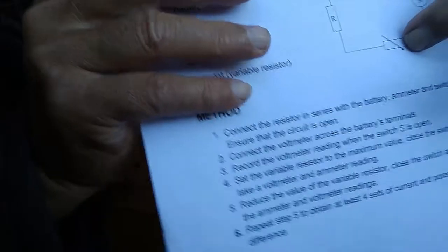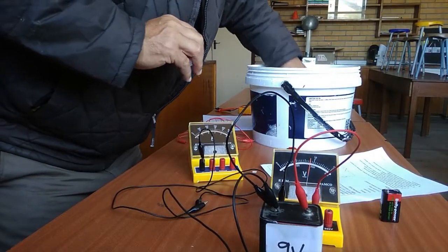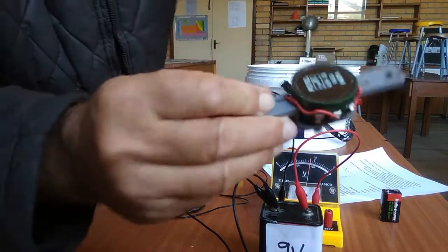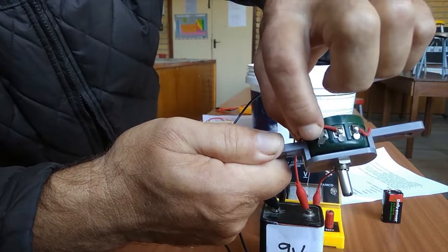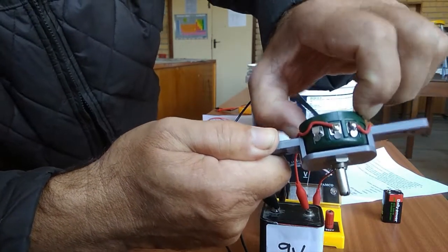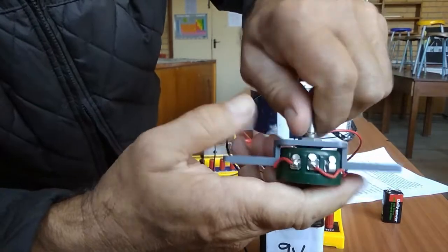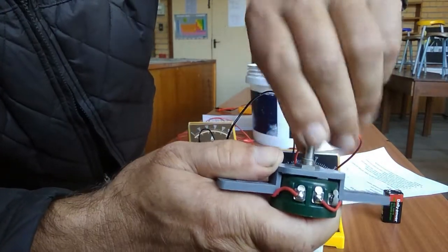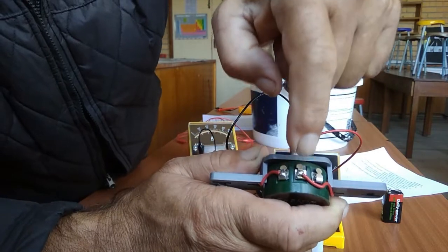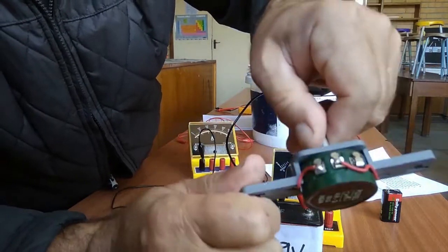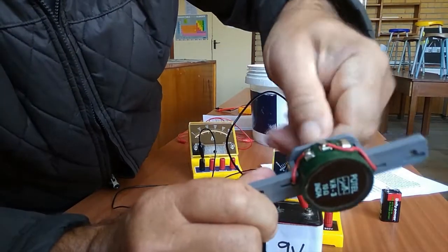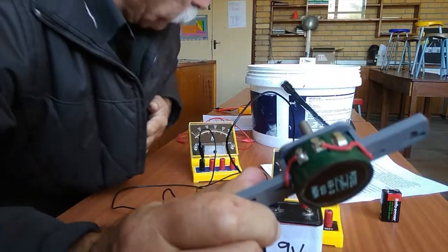Then from the other side of the ammeter, it goes to a variable resistance. So we've got a variable resistance here. Look, it's got 1, 2, 3. The middle is the sweeper, and you can sweep from a minimum to a maximum by turning this little dial. It's lost its knob, so we're going to attach one crocodile clip there and one there, and this is our variable resistor. I tested it out. It goes from 0 to 11 ohms.